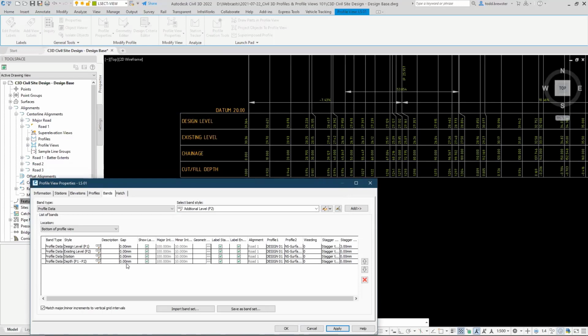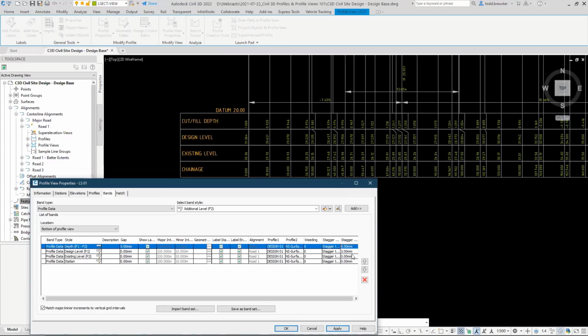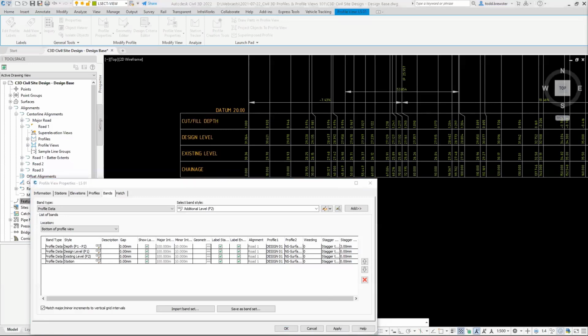All right. I actually potentially want my depth controls to be at the top. So if I grab that and use these sorting buttons on the side here, I can push it to the top. If I apply that and then break my stagger, because the stagger controls need to be applied to the first, not the mid, you'll see that the stagger labels kick in here. What you do is you reset that one to 0 and you put that to your 3, and then you apply that, and then the stagger gets applied to the first one, and then the others keep the same stagger. All right.